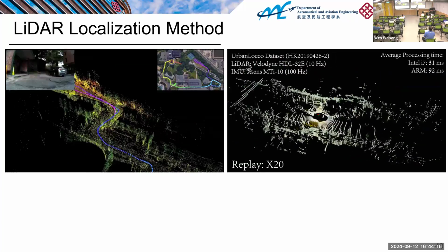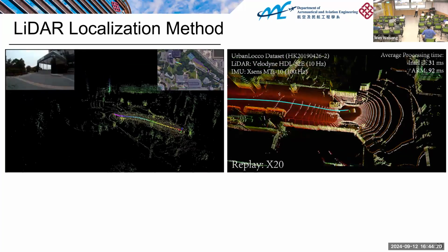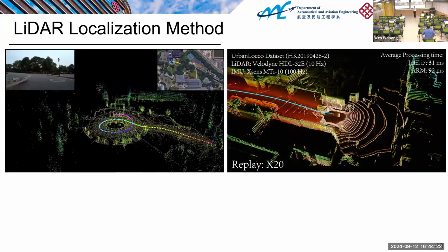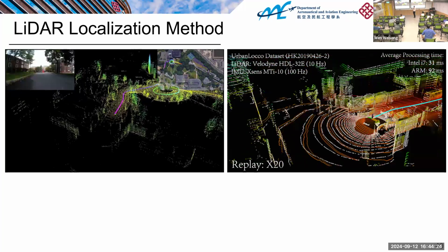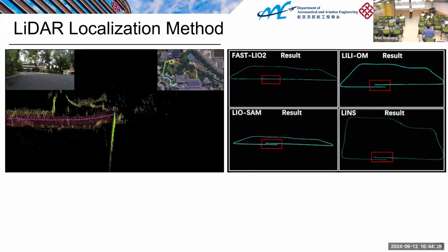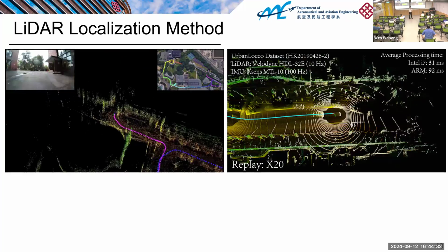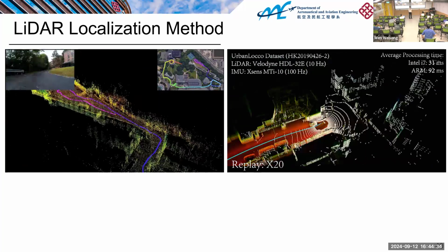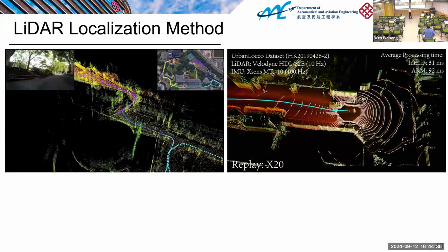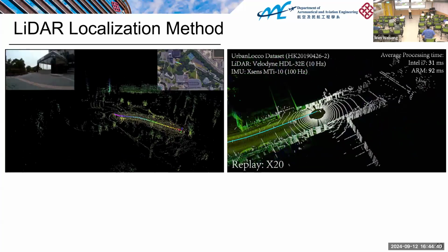This trajectory is the accumulation of several dots, which are the LiDAR collection timestamps. So based on this, we can get the trajectories, right? By accumulating all those LiDAR point clouds, you can easily get the map and simultaneously get your trajectory. And you can also do this based on the ICP from ChatGPT directly.